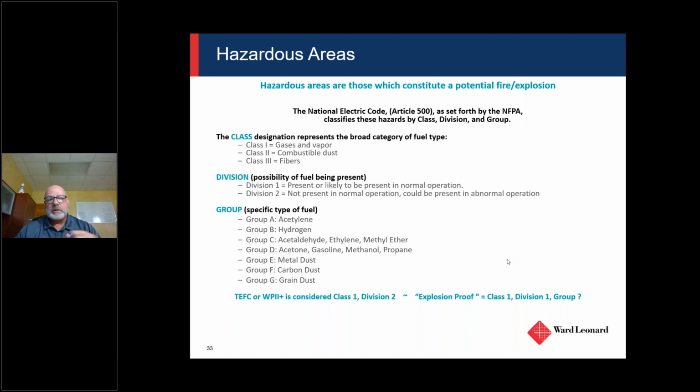When you look at the construction of a hazardous or UL approved motor, there are really long flange areas, even on the terminal box, all very long flame path areas to extinguish that. So the design of the motors is completely different. They do cost more money new, and they do cost more money to repair.